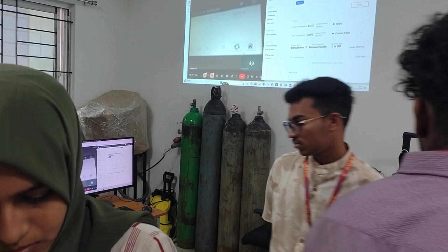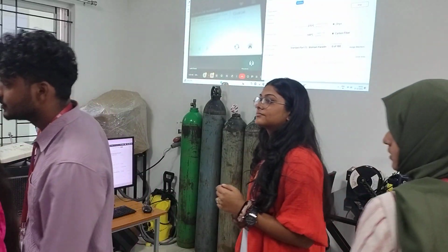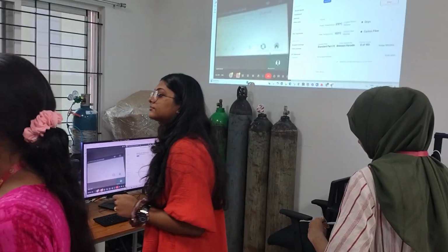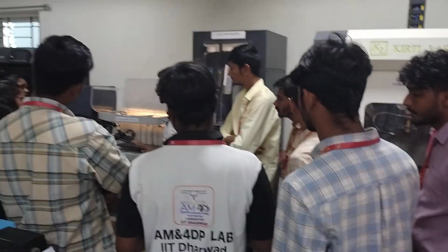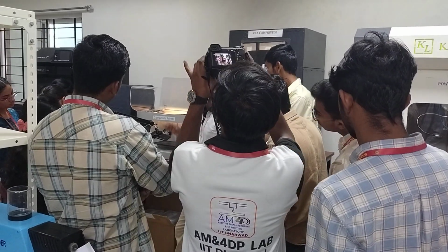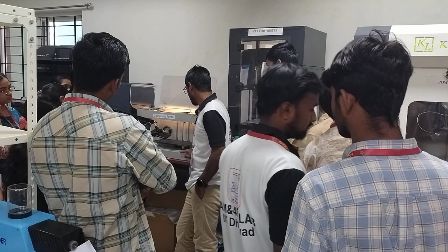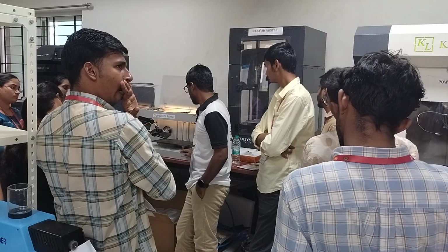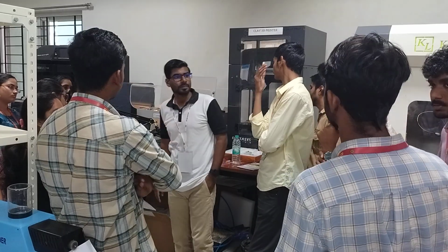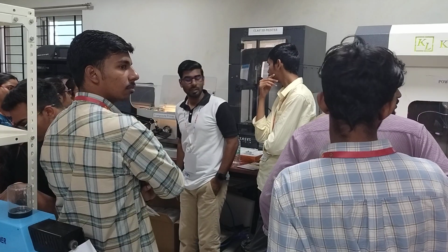The most important thing is that whenever we are printing, since we have done the test prints, we know it is going to print well, but still we have to see whether the first layer is printing properly or not. If the first layer is printing properly, we can say that yes, this printer as of now is reliable and you can go ahead with it. Still heating.